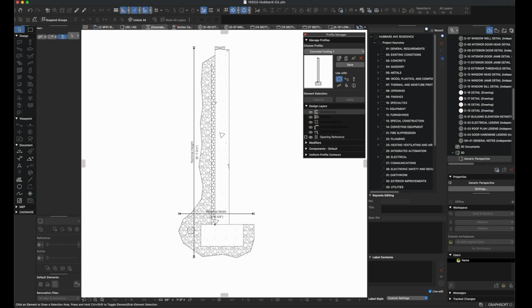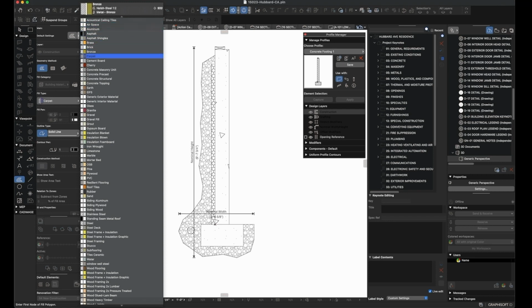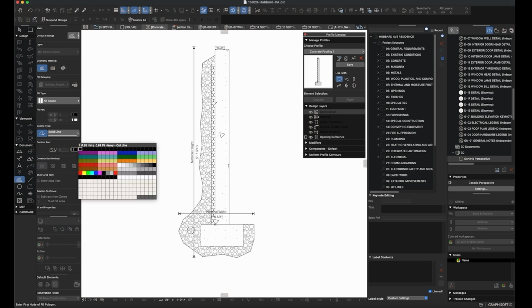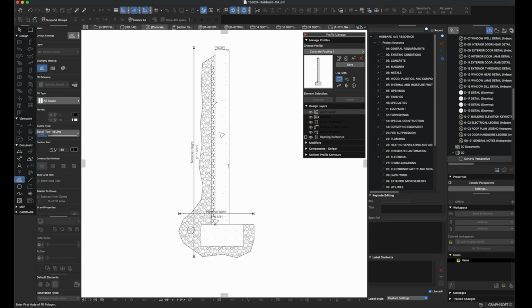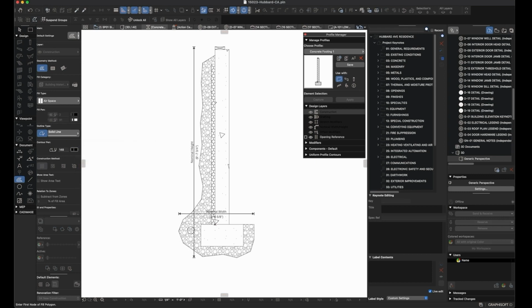It just depends on your local area and the proper design methods that you should be using for your particular local jurisdiction. So in this case, I'm going to do this as a filled region, and we're going to set it as airspace because it is pretty much empty airspace. I'm also going to change my pen type to a thicker pen type. In this case, 148, because for this particular pen table, that gets you a 0.8 millimeter line, solid black. I want this one to read very clear against the hatch pattern of the gravel.